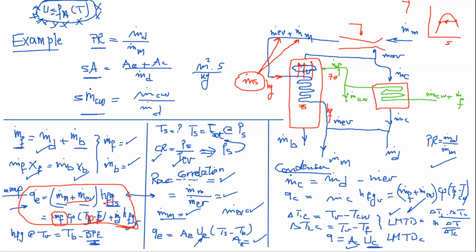So the steam that is entering there is used first to sensibly heat the feed to saturation temperature and then evaporate part of it. The feed is 2.5 kilograms per second, for example, and 1 kilogram per second is going to be evaporated, and the rest, which is the majority, the 1.5, is going to be rejected down as brine because it will not evaporate. Okay. Clear. Thank you.